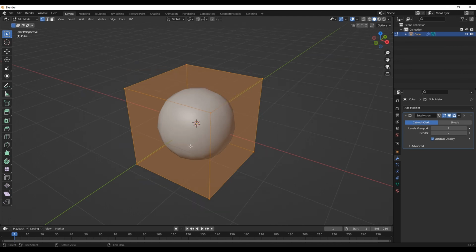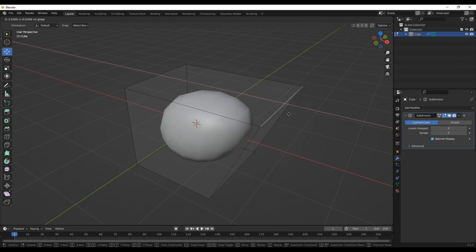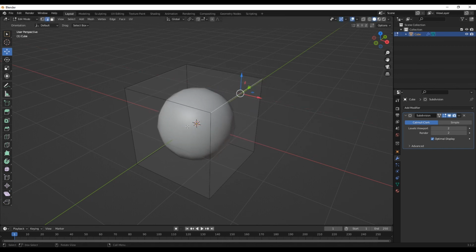So one key thing to note is that the proximity and arrangement of your edge is very important. So if I go to our edge mode here and I just select this edge we have over here. So I'll bring my gizmo in to demonstrate this. So if I just drag this on the x-axis, you can see that the shape of our mesh begins to change. And why this looks like a ball is because we don't have supporting edges here to make these corners tighter.